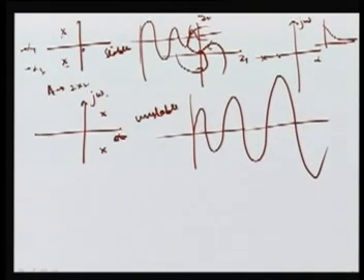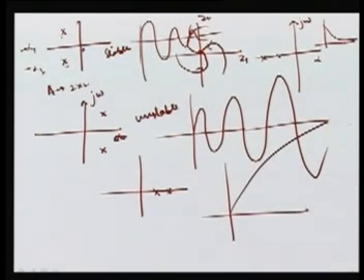For this case, if it is on this axis, and your roots are lying here, then your system will simply go out of bound. It will not be oscillating. Oscillating means you have some complex term, some imaginary term, and that is omega. As I said, the frequency of oscillation is omega upon 2 pi. So if this omega is 0, that is this axis, there will be no oscillation and a direct decay will appear. Again, this is the unstable case.